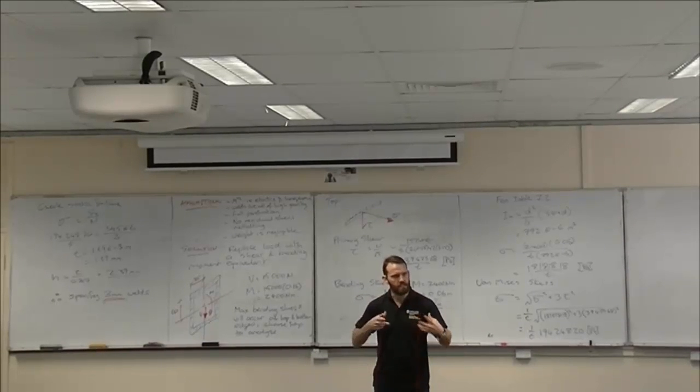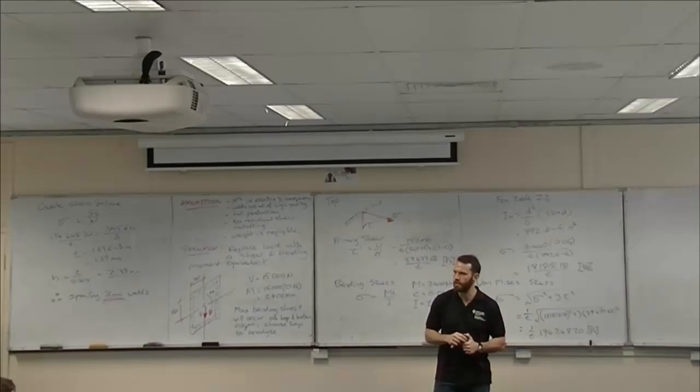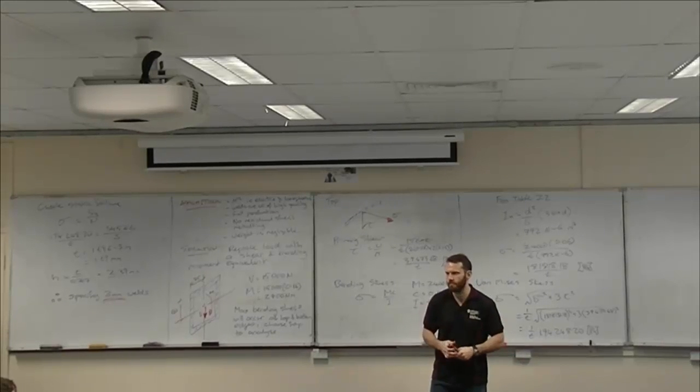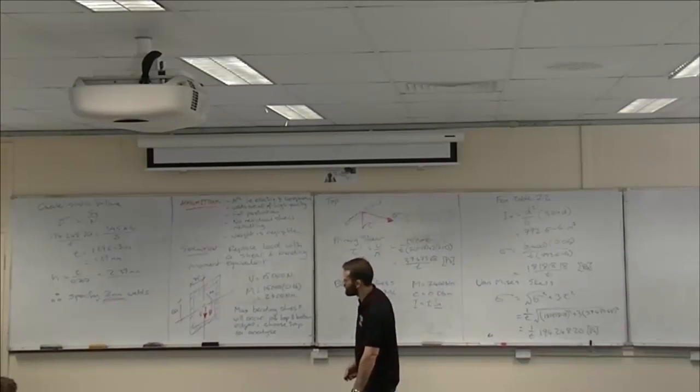So you start to see how strong those welds can be in static failure. And remember, that's only to get to yield too. That's not ultimate. So ultimate might be another, I don't know, 15-20% on top of that load carrying capability. So welds are very strong. I mean, steel is very strong. If you had the steel as a single piece, you'd be pretty confident that that amount of steel could carry 1.5 tonne. But as soon as we start talking in welds, you inherently distrust welds, which is right, because you should inherently distrust welds. But the analysis tells us that they're very, very strong.